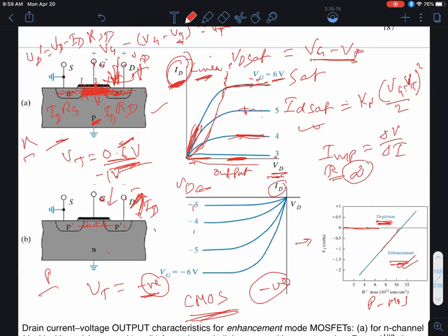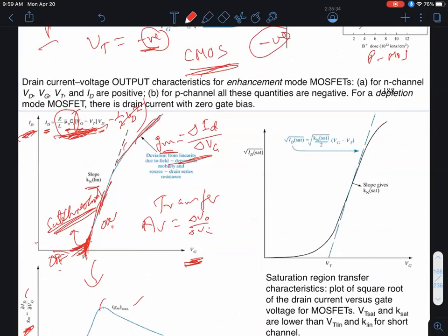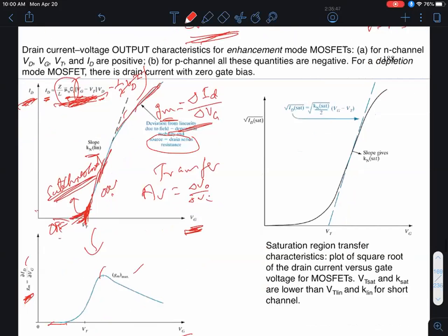So as a result, as the gate voltage goes up and the drain current goes up, there's more and more voltage wasted across the source and the drain regions, and the drain voltage available for the actual transistor itself goes down. That's why the curve bends over. That hopefully will immediately tell you why it's so important to have a low source-drain series resistance, because you don't want to waste a lot of the applied external voltage across this parasitic source-drain resistance. We'll see later on how that is achieved in practice.